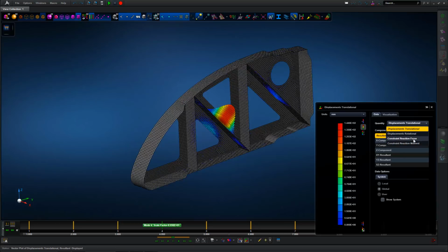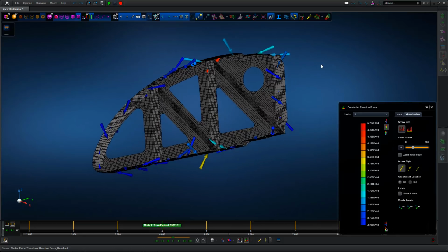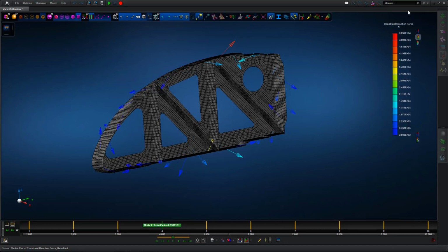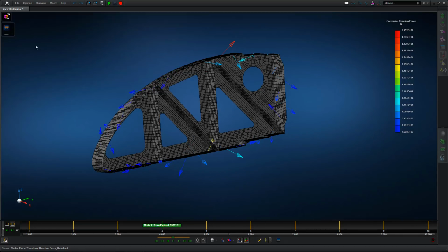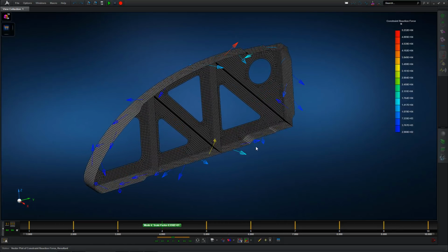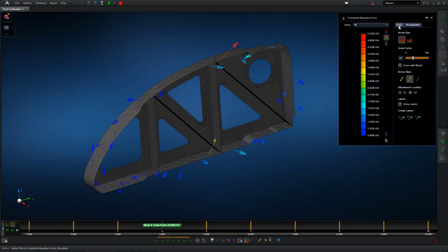but we can look through the model response based on our local and global buckling modes and understand what the structure is doing. And then we're double checking the constraint reaction forces, but imagine this was built into a larger assembly. We would see these as discrete fastener loads coming through for this type of structure and analysis. Again, a level of idealization which gives us more insight into the rib.